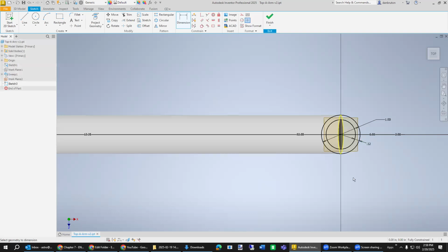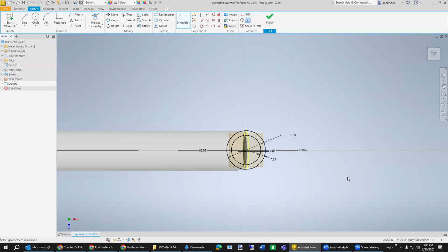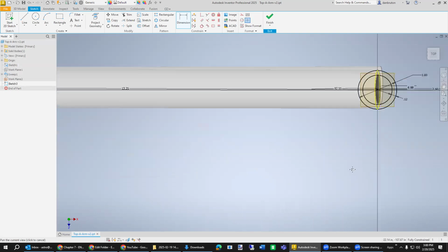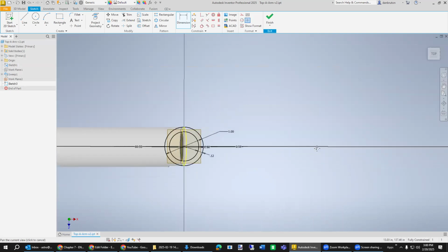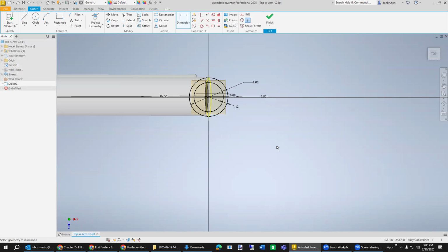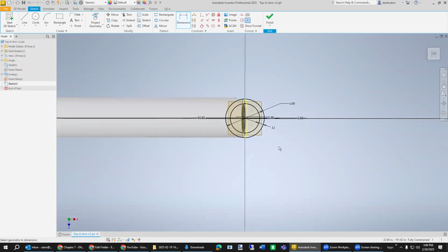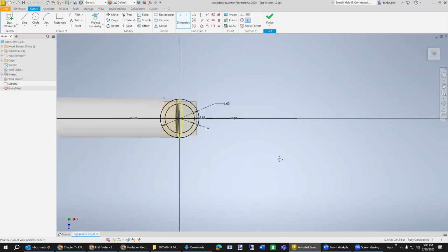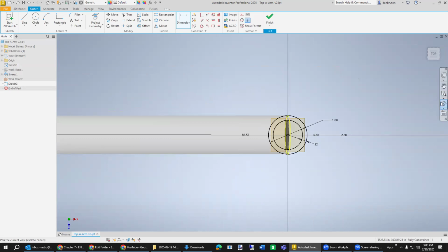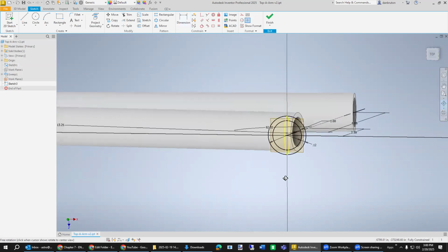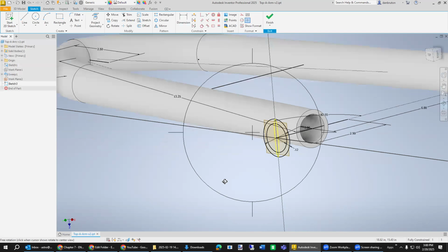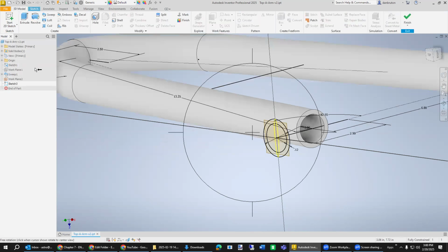Standard wall thickness, and then we orbit over to the side just a little bit, holding down the shift key if we can, orbiting down a bit. Let me hold the other shift, see if that helps. Just a little bit of a motion. So let's try to do it another way. Let's go this direction, or go over here to orbit and see if we can achieve it like this. Much better. So then we go to the 3D model view, select sweep.